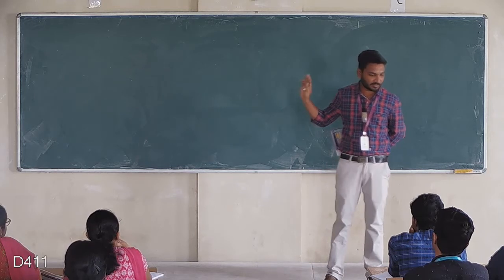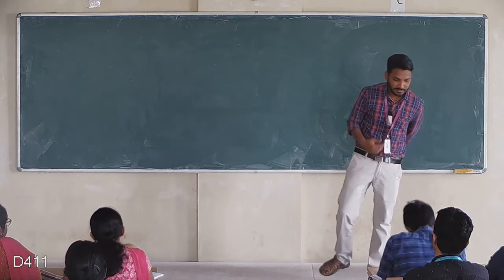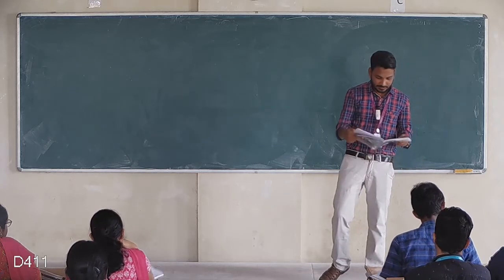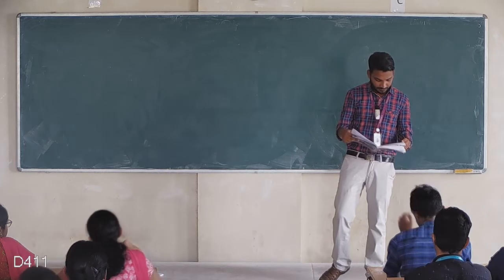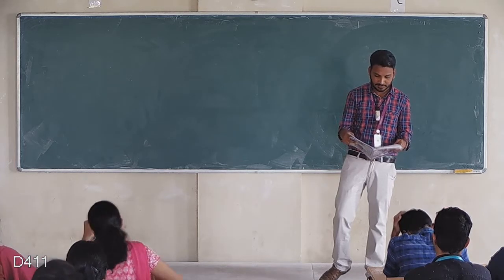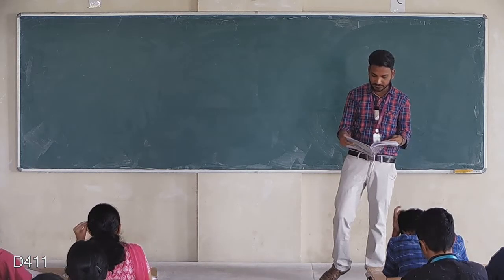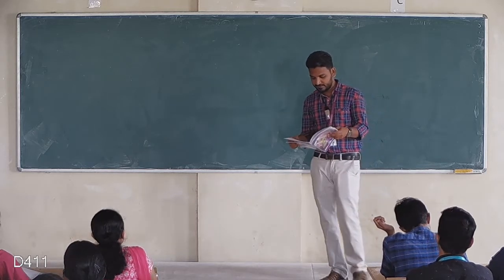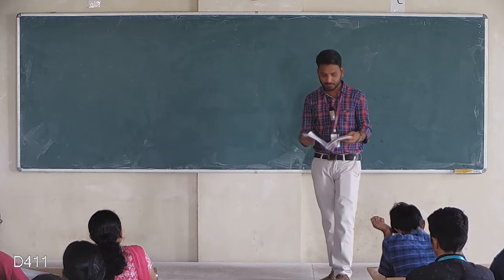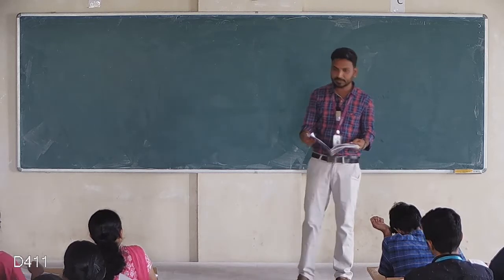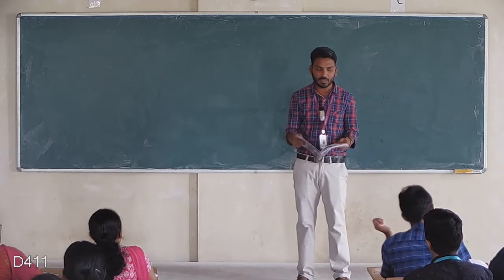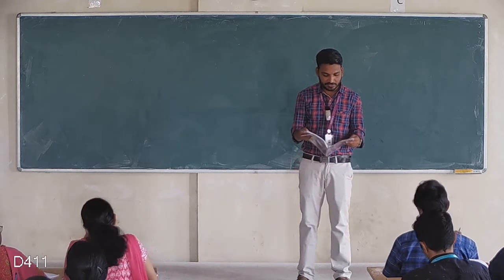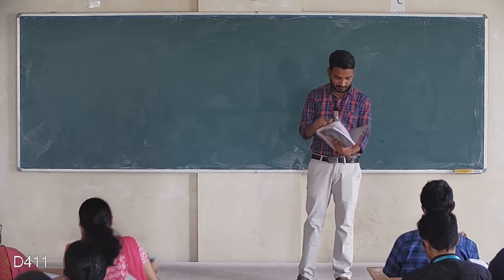We have seen up to last class. Next one, we have derived it. What is the equation for VCE in the collector base bias circuit? VCE equals VCC minus (IC plus IB) into RC. Next one, advantages.